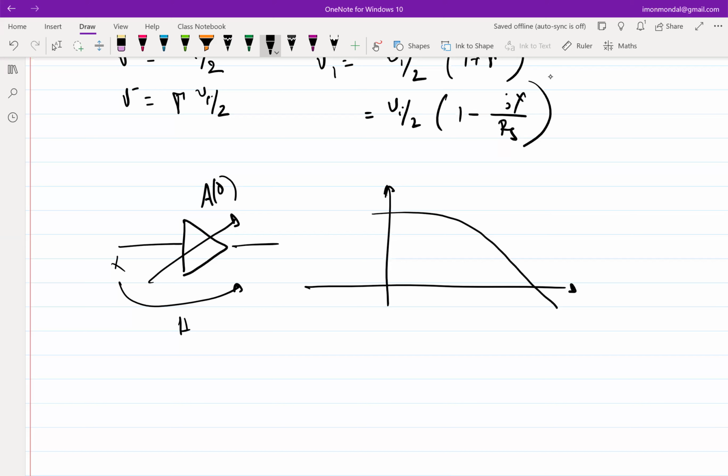So if I say that this amplifier has a profile like this, then there is a problem with this profile if this comes directly at the front end, directly after the antenna. What is the problem? The problem is maybe the signal of your band of interest is somewhere here. This is where you want to be. Everywhere else is out of band, which means somebody else is transmitting there. And which means there can be jammer signals, there can be blocker signals of very high amplitude.